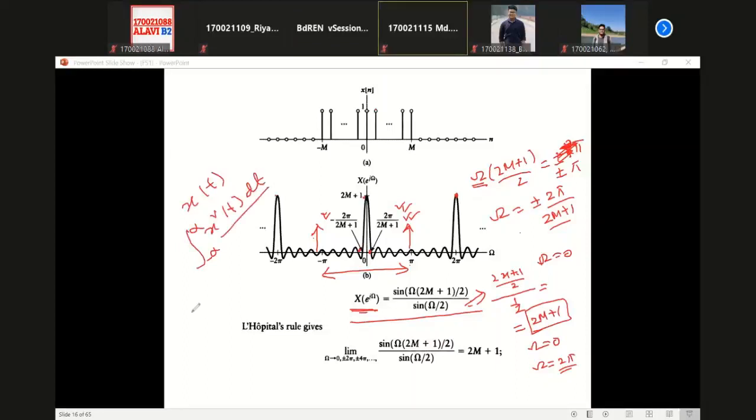Then if we express this signal in another form, say the sum over k from minus infinity to infinity of x_k e to the power j omega 0 kt, for the case of continuous time, and we want to square it, this complex exponential will not contribute to our energy, because its magnitude is always equal to 1. Then the magnitude of x_k squared is what will contribute to the energy, isn't it?